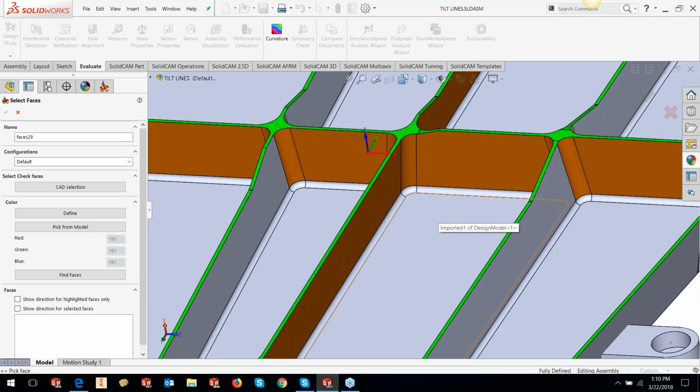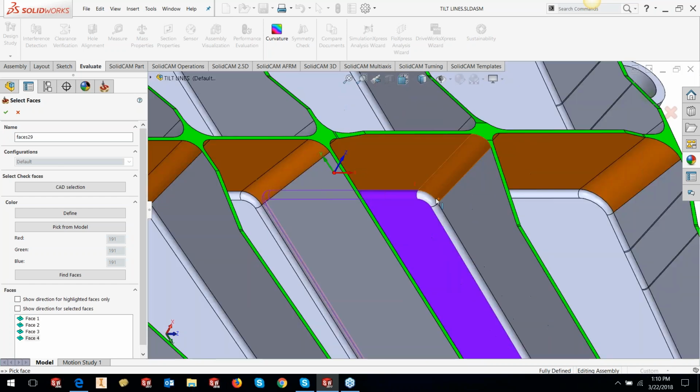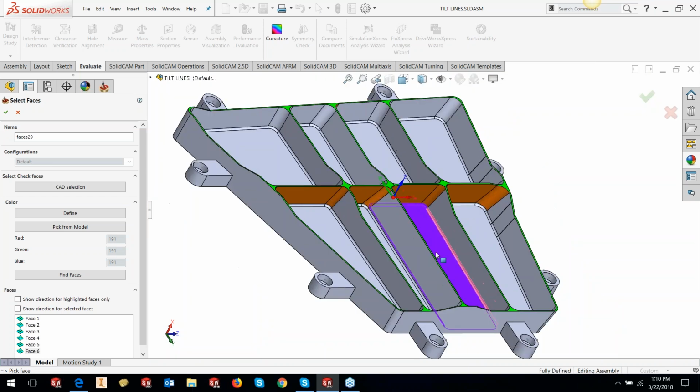So what is included in the floor surfaces? This is a question people always ask. What is actually a floor surface? Is it only the flat surface or the base surface? Actually, in swarfing, anything that does not include the straight flanked surfaces is to be assumed to be a floor surface, which includes the bottom face and the fillets. The fillets are considered as a floor surface.